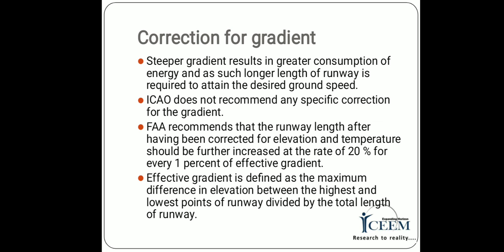Next is correction for gradient. A steeper gradient results in greater consumption of energy, and as such a longer length of runway is required to attain the desired ground speed. ICAO does not recommend any specific correction for the gradient.